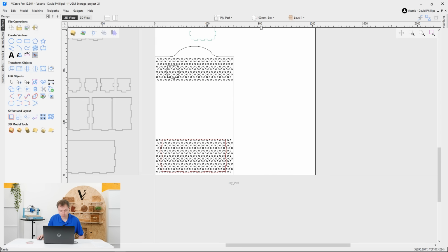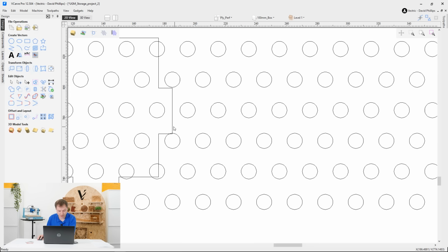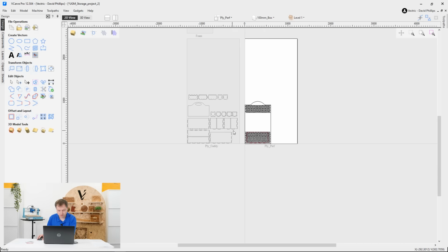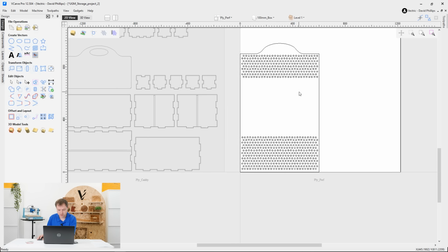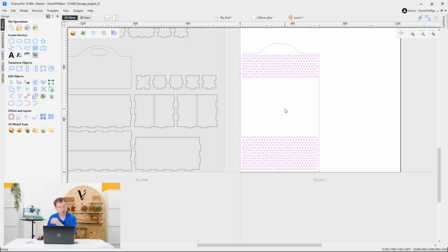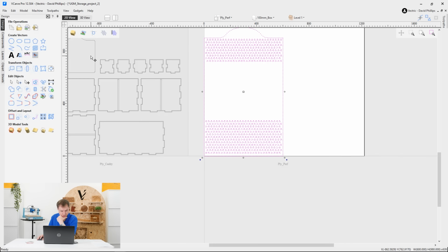So now that we've done that, we can delete these out because we don't actually need these on the sheet. We're not going to be toolpathing them. Could just switch the layer off, but just to tidy things up. There we go. Right, the next part of the process is actually going to be using the Keyhole toolpath on this. But because once you've applied that, you can't actually move the toolpaths, we're just going to move the entire layout in so that the profile is not going to be off the workspace. It's going to be offset from the XY datum position.